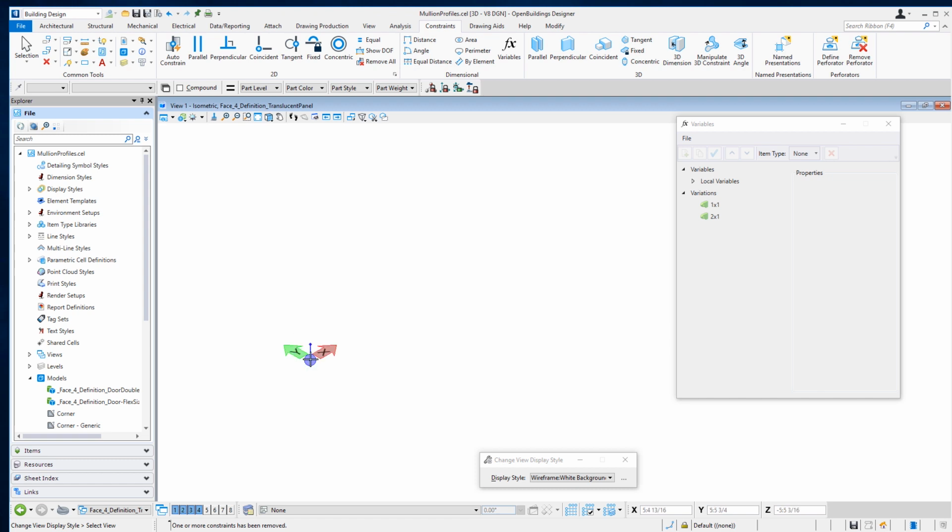Now we want to note that 0, 0 origin. We do need to create this panel with that 0, 0 origin at the lower left. Now the first step is to create a shape, and that shape will represent the rough opening of our panel. It essentially means the area between the frame. And I'm going to go ahead and just create that shape on the default layer.